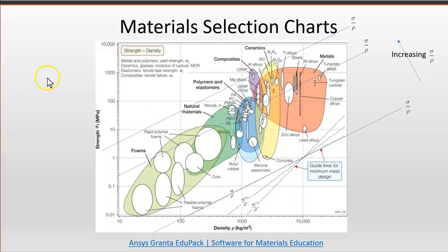and cyclical loading. Due to the large number of options of available materials, systematic methods have been developed to allow material selection. One of these is based on material indices or indexes. The way it works is we will plot relevant properties of materials against each other from a database.